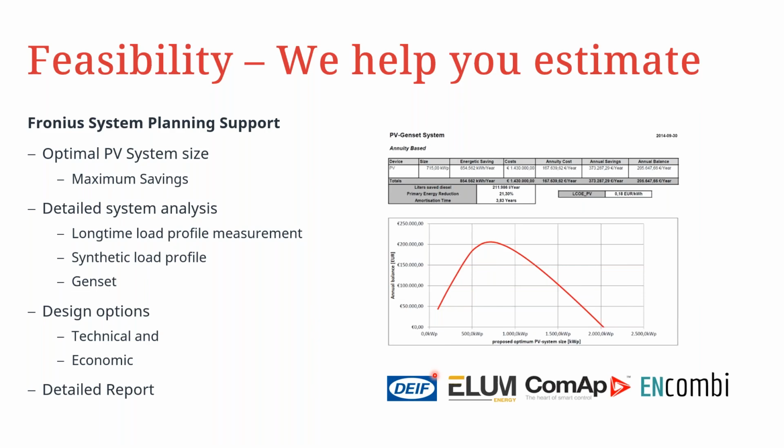So Fronius recommends the following controllers into the system. So we recommend DEIF controllers, as well as ELIM, COMAP, and lastly, InCombi controllers into the system. If you're doing your own generator integration system, we do recommend that you get in touch with the tech support in Austria. They will then be able to assist with guaranteeing that it will be able to do the control of the system entirely, and they will again give you the green light if it is usable in the system.